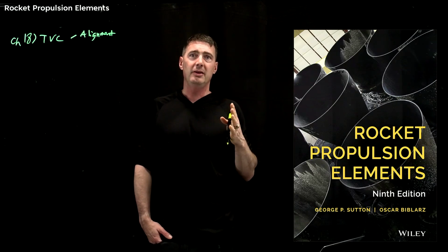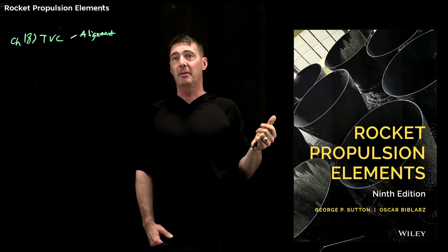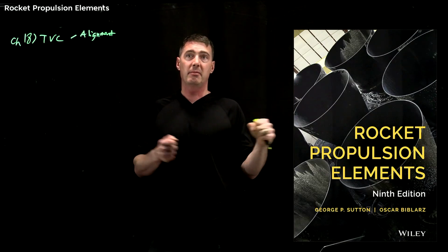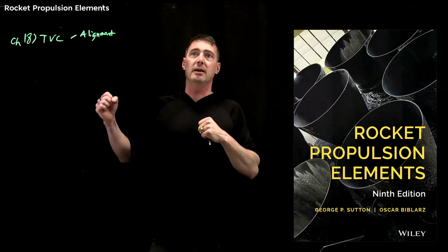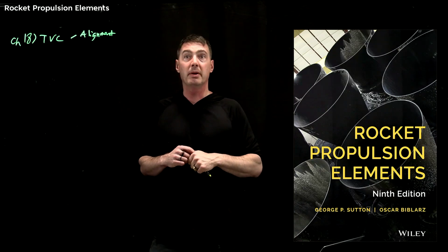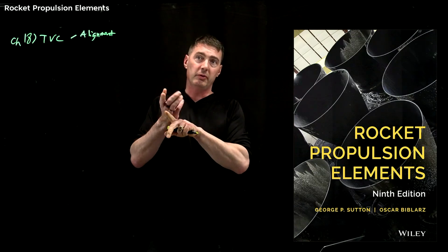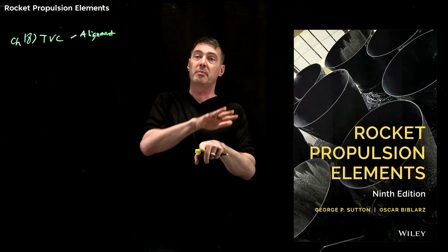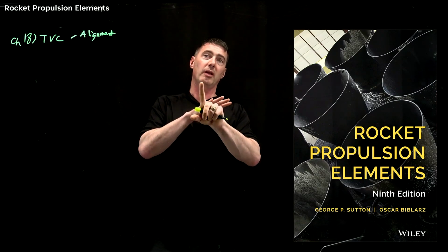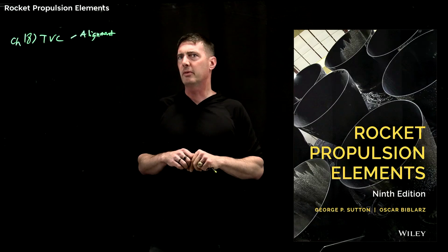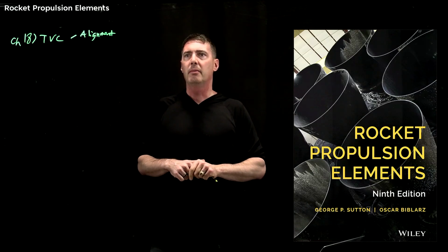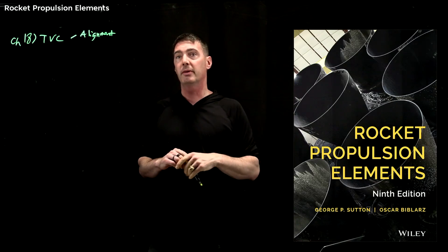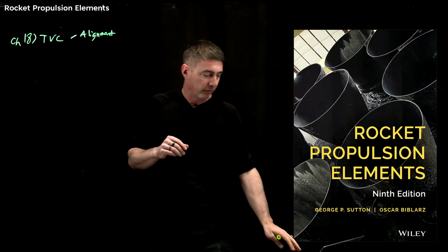Now, in addition to that, if you're SpaceX and you're trying to land, and I've seen the Starship landings, it's a 30-degree gimbal in order to have that much control authority on how to move the vehicle around. So it can be pretty large. At Virgin Orbit, we dropped off the wing of a 747, and our first thing we had to do was count to 5 as the 747 was banking away and then execute a pretty gnarly pull-up maneuver. So I think our gimbaling was up to 8 or 10. That's not normal. A normal vertical rocket launch would only need to gimbal up to 3. But those are all gimbaling, so there's really a broad range.